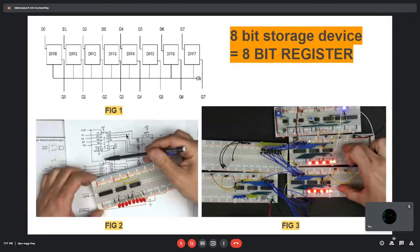In the right side if you see, he has shown 2 of these registers, so total 8 plus 8, 16 latches are there. In these 16 latches, 2 values are stored, the same value, it's 1 0 1 0 1 0 1 1, and again 2 values are stored. You can store any kind of values. So this is an 8-bit register.